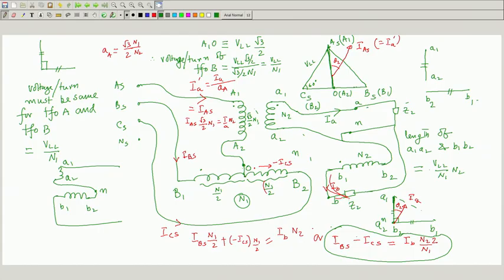See, what is the statement of the problem? You get a balanced 2-phase voltage, connect a balanced 2-phase load, secondary currents which are balanced. This will be I_A, where will be I_B? 90 degrees away. I will make it more clumsy on the same paper so that you understand. I_B will be here of same magnitude, lagging the B phase voltage by theta.